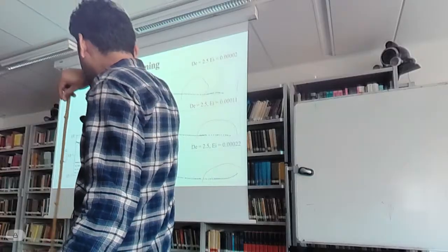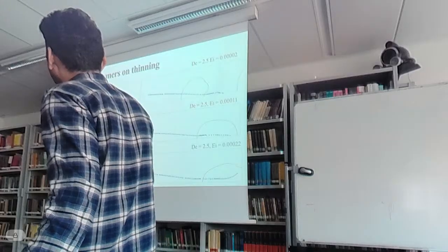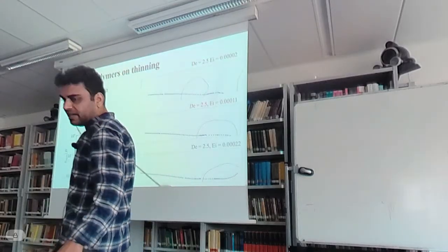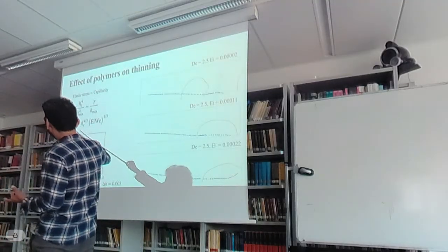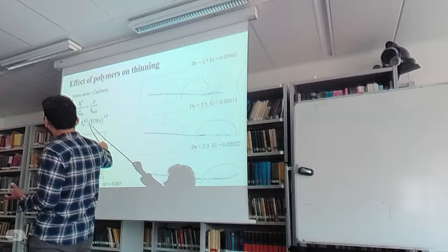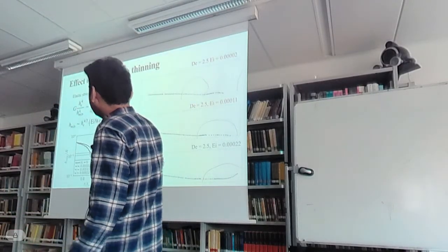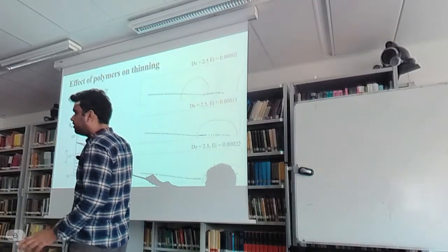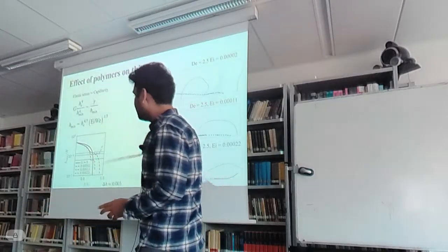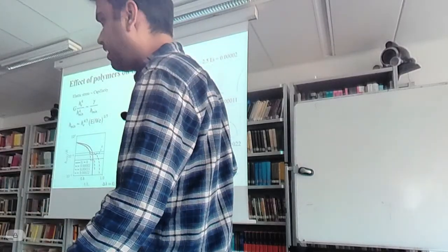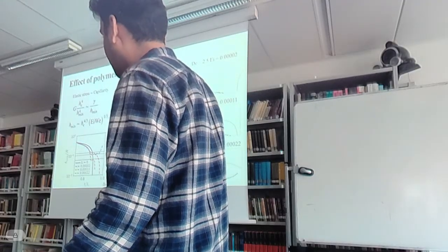And if you go back to the elastic theory and compare the elastic stresses to the capillarity, you can obtain a constant height of the interface depending on the elastic inertial number, and this height matches well with the plateau that you were trying to go to. But all of a sudden you have this other solution that it breaks up or goes down, and this puzzled us for some time.